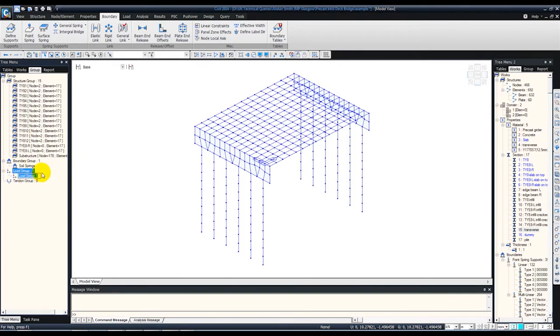So new, so this is self weight of the precast girder and other concrete elements. Then we have wet concrete, that's for the slab, infill slab. Then we have earth pressure, which is calculated from the PD document. The K star values are calculated for passive pressure and applied on both the abutments at the same time. Then some other loads like surfacing can also be applied. Let's go with these loads and then we will apply some more.